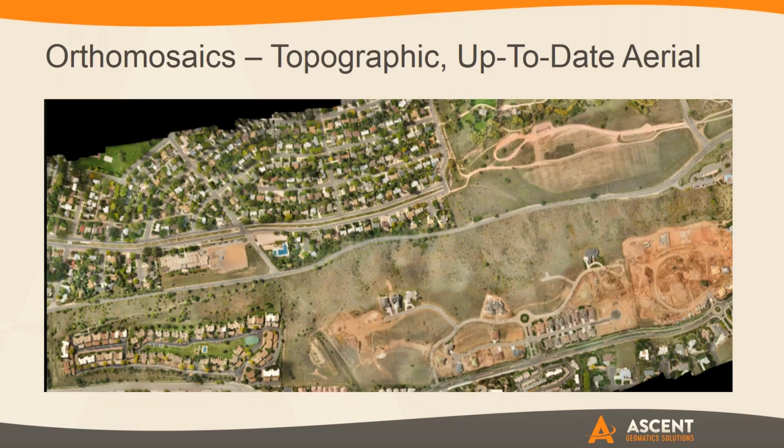And then orthomosaics. If we're collecting photogrammetry, we can compile these orthomosaics of the project area. Once again, this isn't just photos. We're tying it down with ground control and getting check shots on the ground. Like you said, we're still doing a fair amount of groundwork, but we can develop full DTMs and surface models from that. So those pictures that create this great orthomosaic also become the topography and the contours that you need to put into your electronic files.